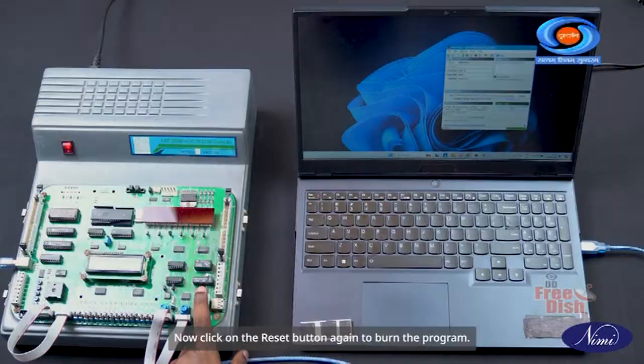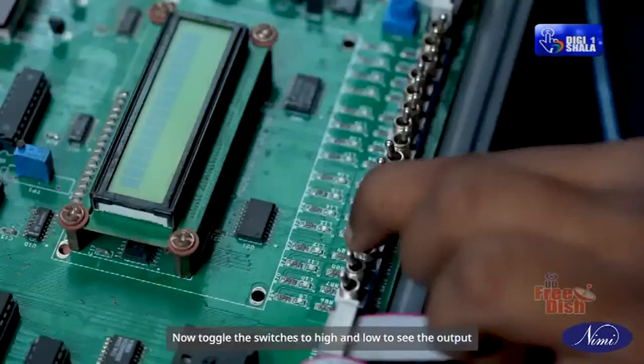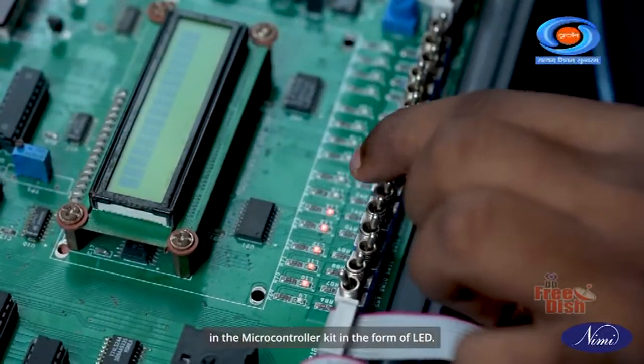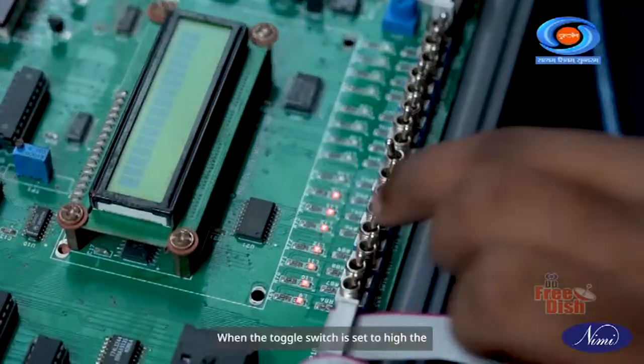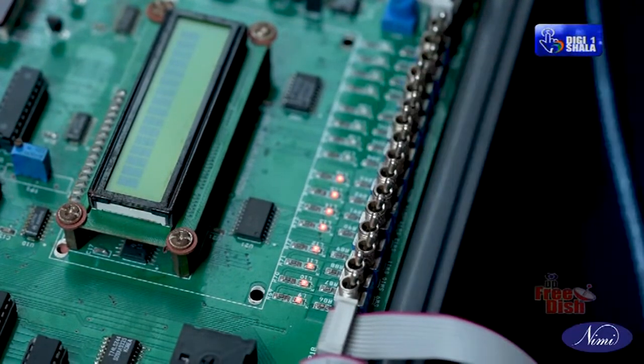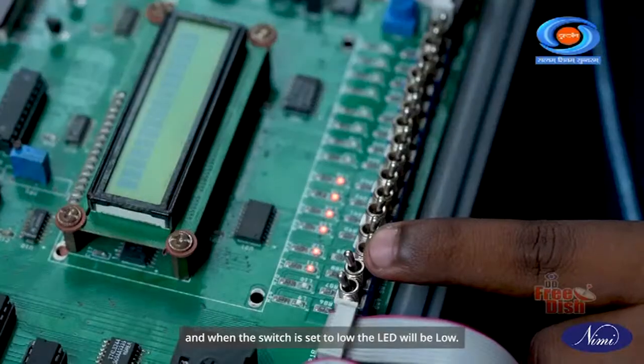Now click on the reset button again to burn the program. Now toggle the switches to high and low to see the output in the microcontroller kit in the form of LED. When the toggle switch is set to high, the LED will be high, and when the switch is set to low, the LED will be low.